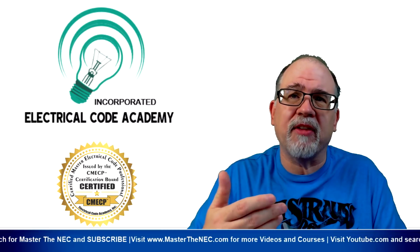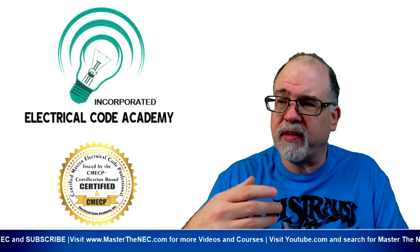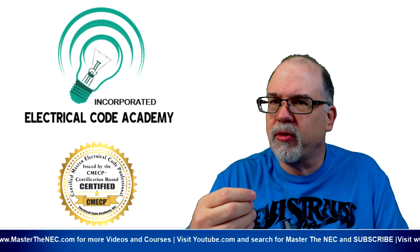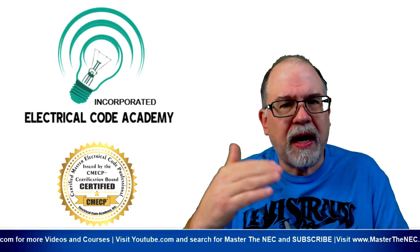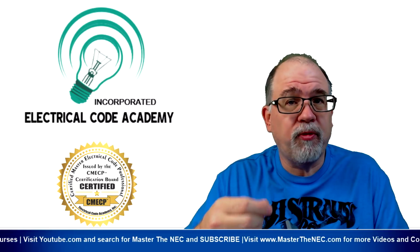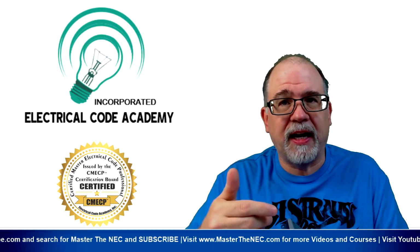I mean, the time is of the essence. If you can get done with the exam and save yourself some time, that way you get more time to check over your questions, then it's a benefit to you, right? So just remember, if it's 480 and you're doing the transformer calculation, remember 831 is the bottom equation in that division. If you need to deal with a 208, remember it's 360. If it's a 240, then remember that it's a 415, and that's what you're going to divide into, okay?